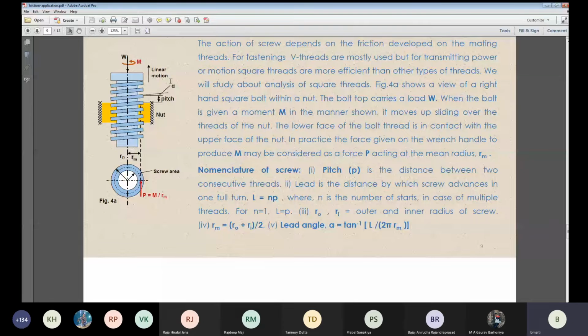The petrol tanker unloads at the petrol pump in a similar manner. They have very long hose pipes, and at the end they couple with another tanker, I mean another system which is at the petrol pump. They will be simply coupling with the tanker using this type of quick engagement screws. They will just give one turn, it will go for a larger distance and it will pick up. So for quick engagement and disengagement, this type of screws are taken.